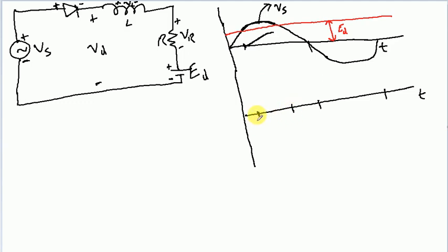So during this interval, the time duration in which the inductor current is rising, which is the current through this whole loop, that is why I'm labeling it as inductor current. As long as this current keeps on rising, we have inductor voltage which will be positive.